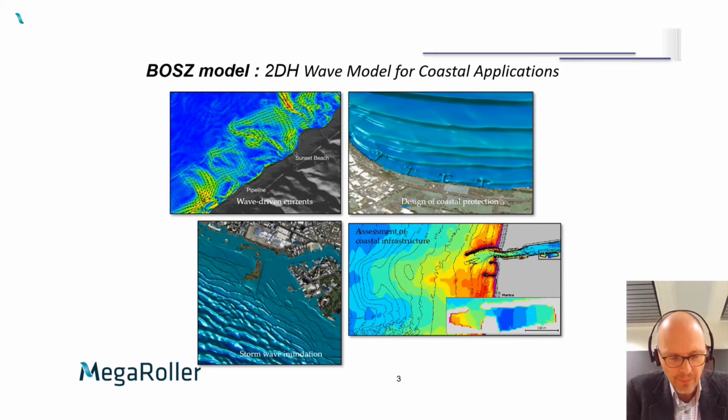Like I said, our work package was focused on the wave resource, and the BOSS model that we've been using essentially gives you a phase-resolving forecast. Typically with regard to wave forecasts in the oceans, you have phase-averaged forecasts on a grid of, let's say, 1 kilometer size, and you get a forecast maybe every half hour. So every half hour on a grid that has 1 kilometer between the grid points, you get readings of the significant wave height, the wave period, and the peak direction.